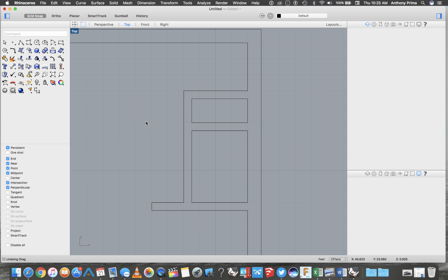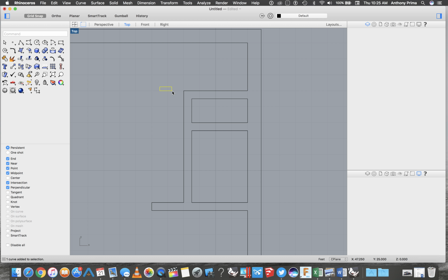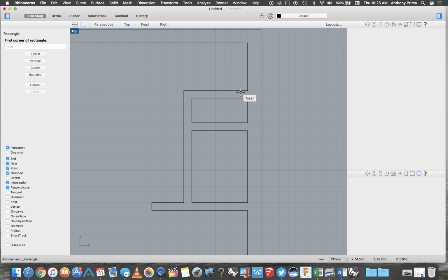Turn gumball off. Also, I have the grid snap tool on up here. I have it set up so that every 1/4 of a foot, it automatically snaps to that. So that's one way we can use for measuring too. Let's delete that. Alright, so I'm going to make a 2-foot opening on this.